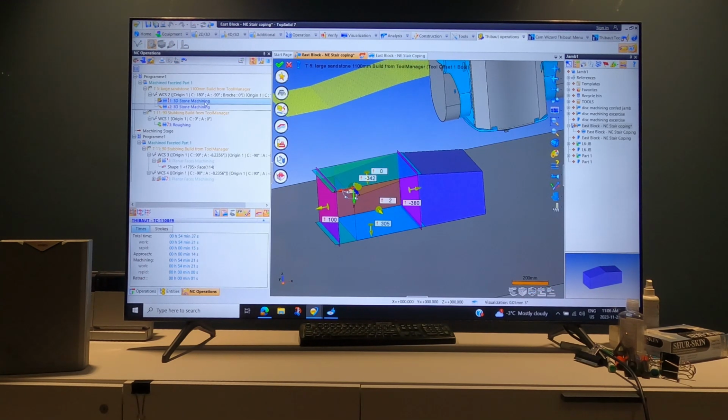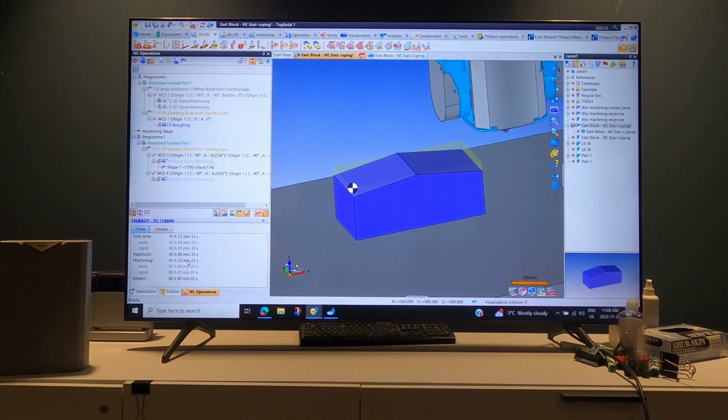Yeah. And like I was saying before, you could do the blade and have larger steps and then use a chisel to get rid of it. And then come back with milling tools. It could be even half and half. What if, because we're allowed 1 to 5 millimeters deep, we were to do it like 4 millimeters? Would that be twice as fast? Oh no, it would make the steps bigger.